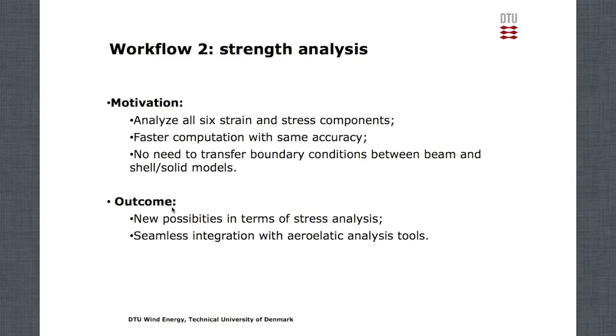The motivation here is to be able to analyze the 3D strain and stress components at a much lower computational cost, and also you're able to apply the transverse forces and moments directly from the aeroelastic analysis code without having to go through complicated approximations using the shell model, for instance.